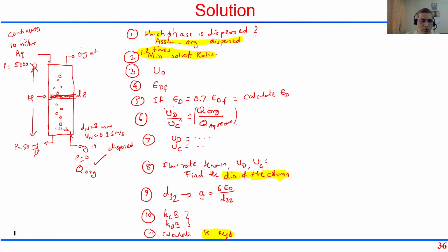Now, this is just a simple set of calculations. These are simple algebraic equations which we can all solve, which we can all find values. What I want you to do is change this 1.2 times the minimum amount. So I have taken 1.2. We can calculate the diameter of the column, and we can calculate height of column.